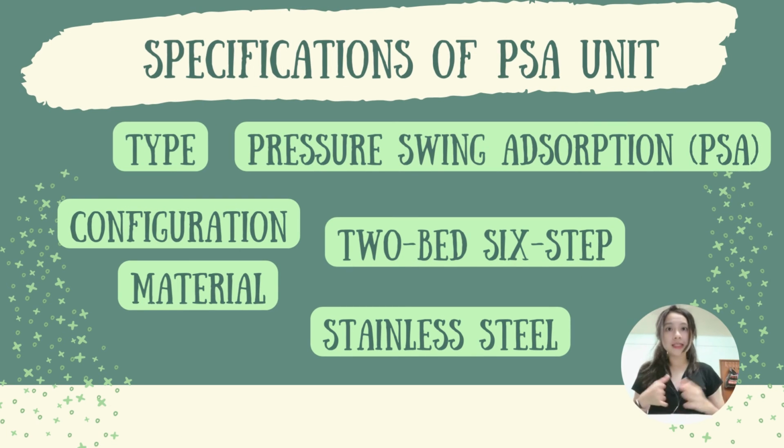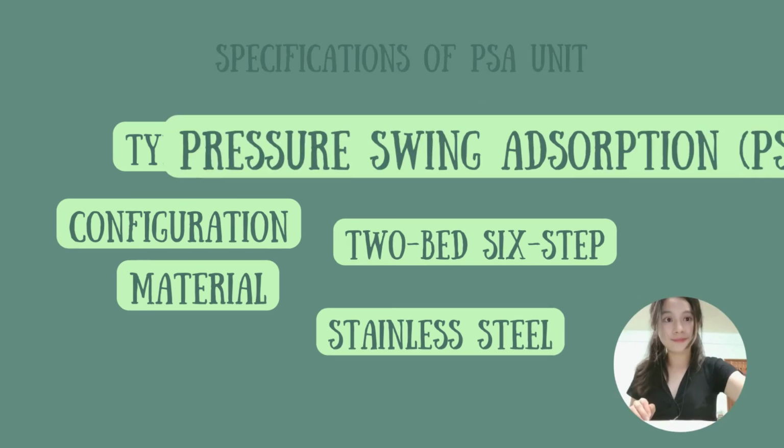For your information, the adsorbent plays a significant role in the adsorption process, and its selection will determine the performance of the separation unit. In the separation of a multi-component gas mixture, two adsorbents are chosen as a single adsorbent is difficult to purify hydrogen due to the presence of several impurities in the mixture. Therefore, activated carbon and zeolite 5A are selected as adsorbents due to their high porosity and selectivity.